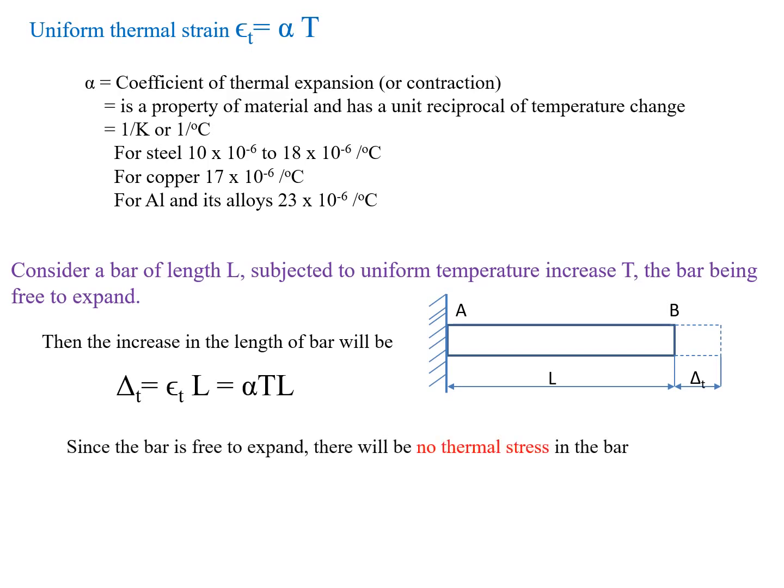And one more thing is very important that you have to remember. When the bar is free to expand, no thermal stresses are generated in the bar. Why? Because there is no restriction for the deformation. There is no restriction for the deformation, so it is freely expanding, and no thermal stresses will be generated. It is very important for all the competitive exams, so kindly remember that. If the bar is free to expand, there are no thermal stresses.